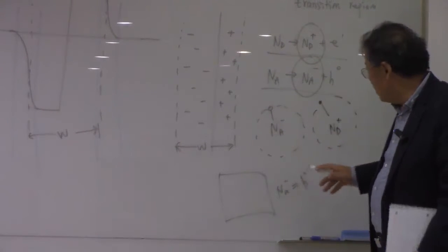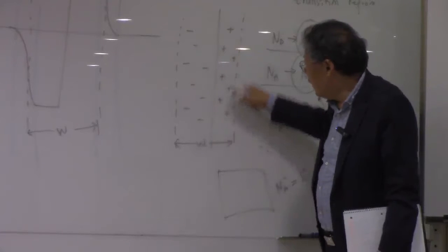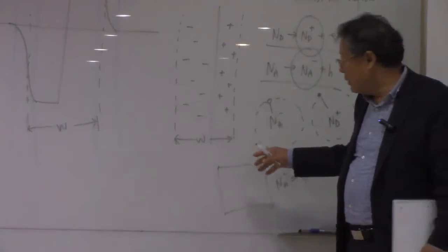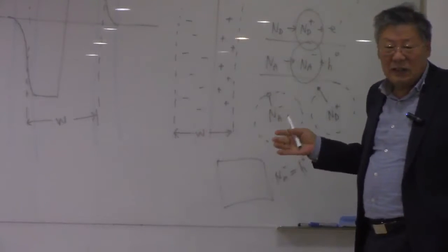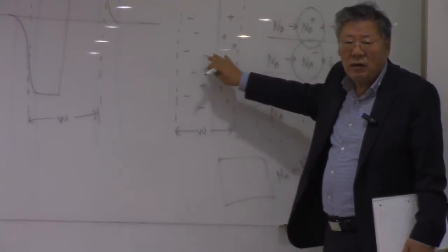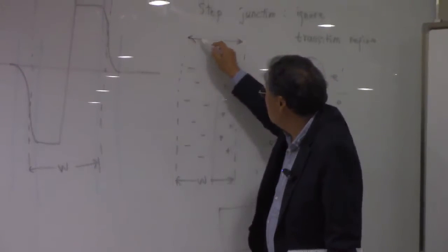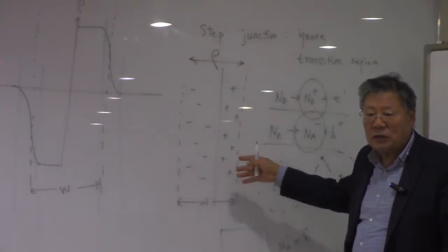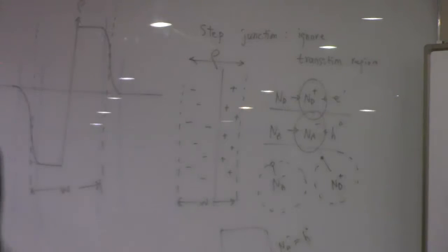Okay, that's what happens in the semiconductors. But when you make a junction, these electrons and holes are free to move, so that they annihilate at the junction. So along some distance, there is a region where the free carriers are null. There are no free carriers, and only the ions are there, which are the donors and acceptors. So we have net charges here, and the charges coming from these donors and acceptors can be expressed by Poisson's equation here. All right.